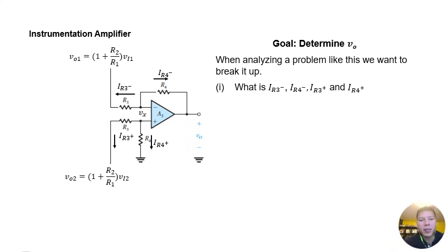So that's this equation here. So now we actually end up with this new circuit where the two inputs to the new circuit are now these, VO1 and VO2. And so now we can actually analyze the rest of the circuit. Now, since no current flows through here, remember that one of the properties of the op-amp is that zero current flows into the input terminals. What that means is that whatever current flows through this terminal has to flow through this terminal.